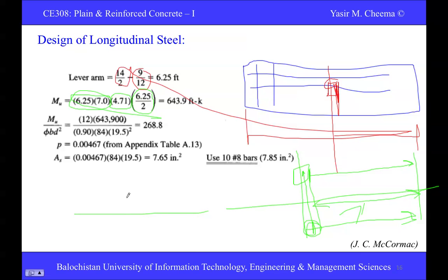Here is the column face, and this is the column. Don't get confused. Now this is the footing, from here to here. It's 6 point something, that is 6.25 here. So these are vertical loads acting, let's say. So the moment produced over here would be equal to, actually it is soil pressure, not vertically downward, it is vertical upward soil pressure.